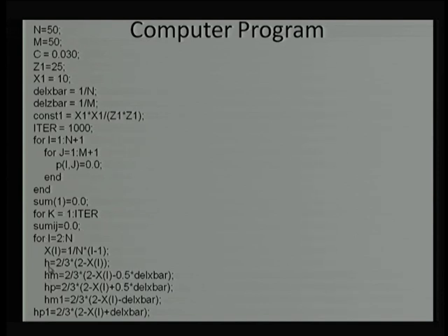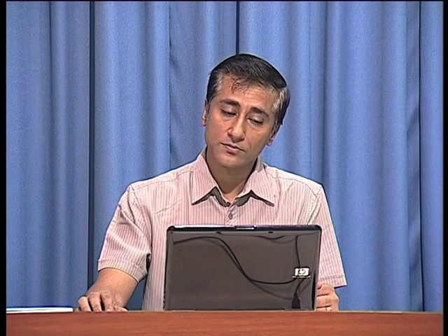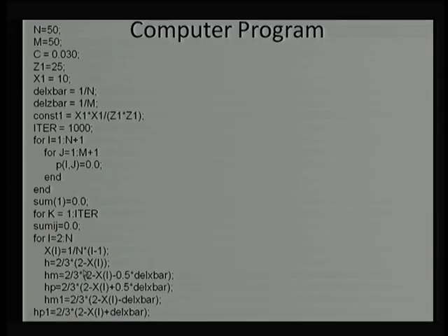film thickness, for which we are taking the same example which we have quoted earlier for approach 1, approach 2 and hybrid approach. However, for the common purpose this h will change if we have some other example; the expression for h will be given over here. So, in this case h is equal to 2 by 3 (2 minus x bar), where x bar is represented with this.